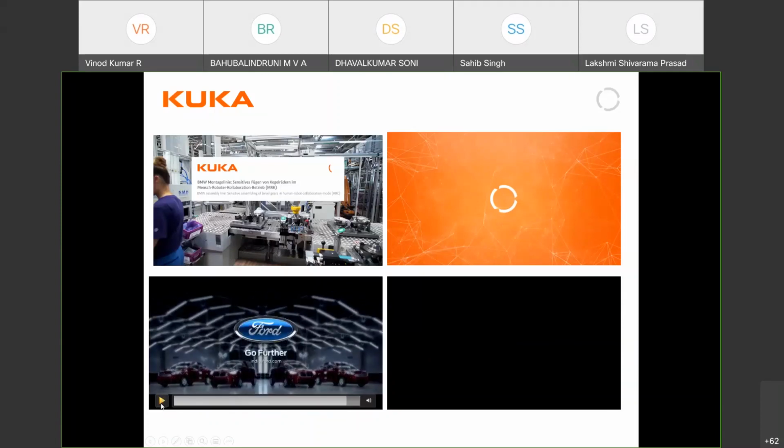So at the end, you could have seen the cobot was just being handled by a very small force, might be just a small touch. So it is taking the force in that particular direction and it is moving in that direction. Once we stopped applying the force onto the cobot or onto the end effector, it started performing its own work, which was pre-programmed already. So this is mainly how the collaborative robots work.